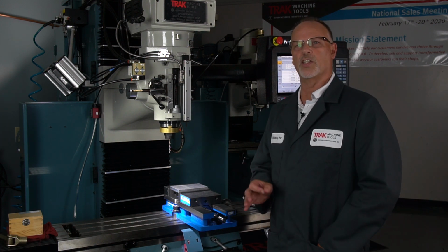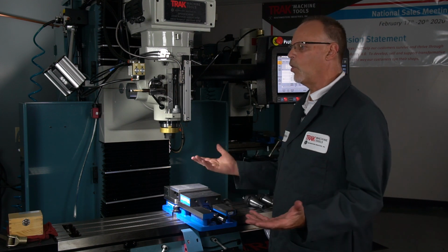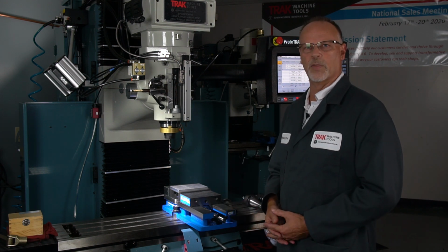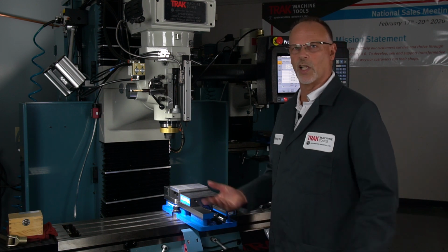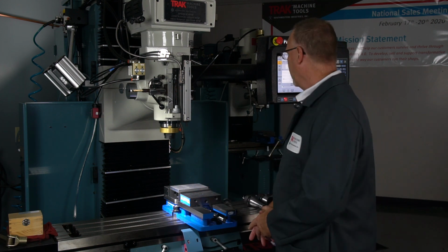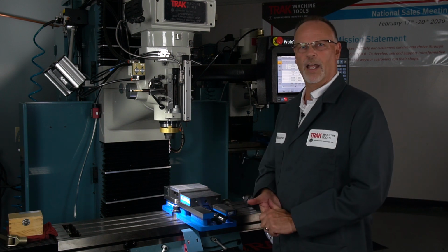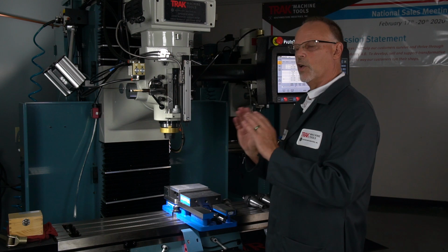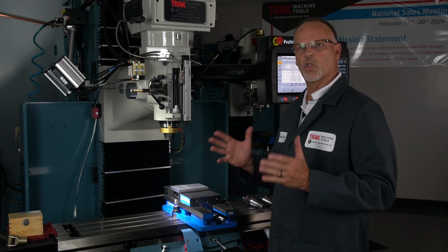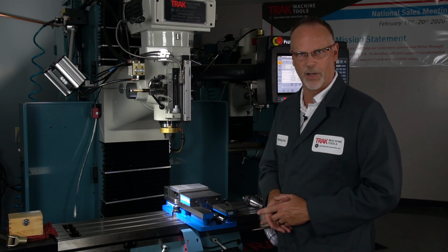I would also suggest that you use the temporary file when you're programming and making big programs, because every once in a while just stop and say Save Temp. It's going to store your work just like any other thing you do in a computer, right? So if something happens and you accidentally erase something or the power goes out or whatever, you're going to have everything that you have done so far as soon as you open that temp file.